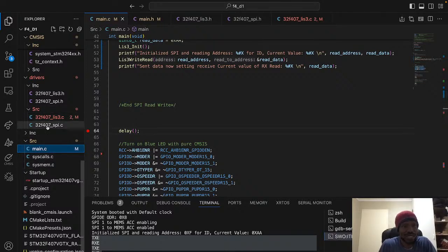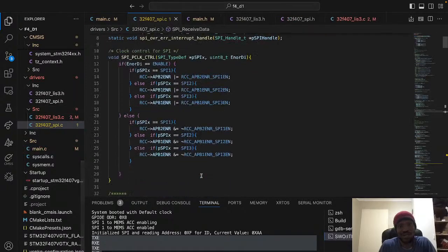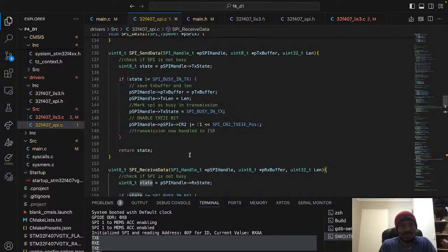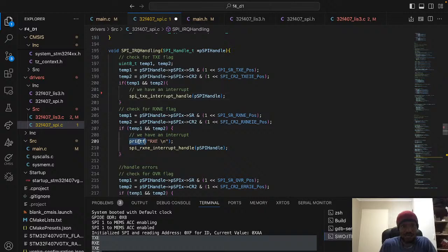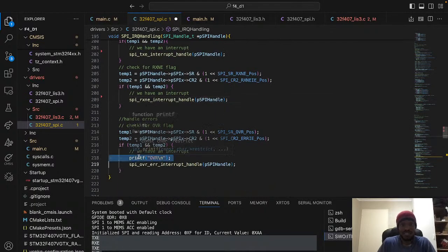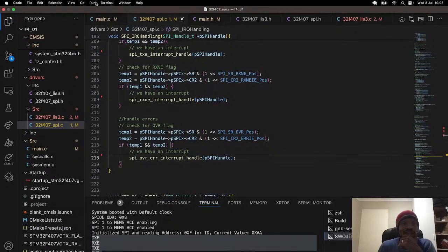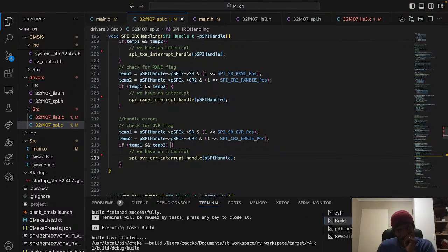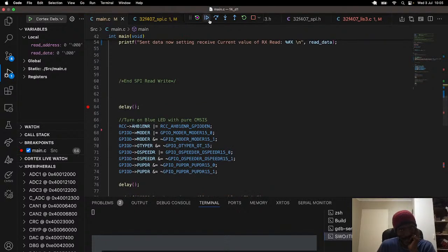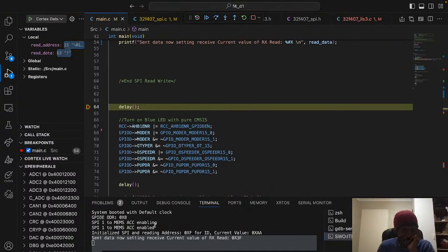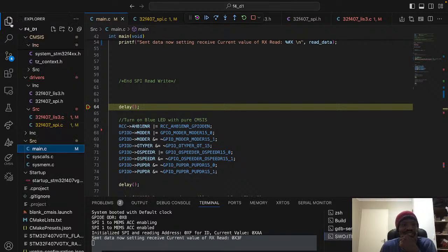Now that we're going deeper and deeper and more of the base of our code is working, we don't need so many confirmations per se. And this is, of course, going to make our debugging quite easier. Okay, cool. So let's run this again, start debugging. I think I have a breakpoint somewhere down there. Cool. So I can just do play. Oh, perfect. What do we see? SPI is being initialized. We don't need this read of ODR anymore because that was all sanity stuff, so we can remove it.